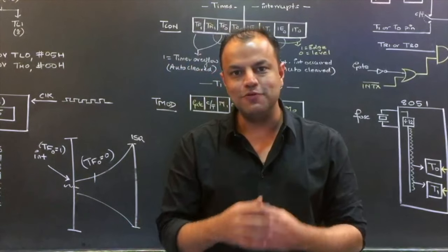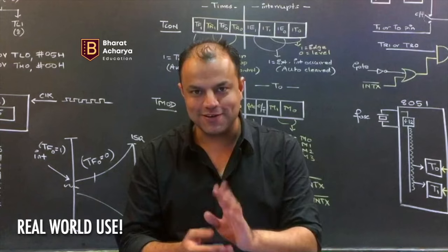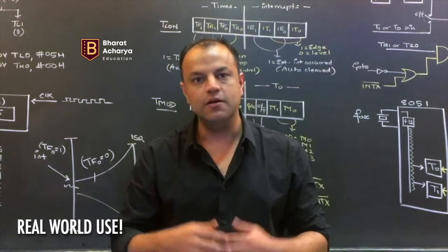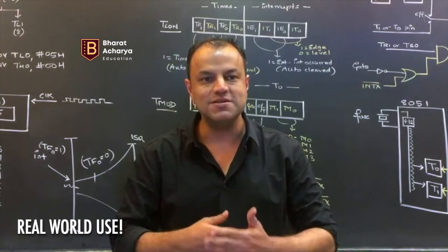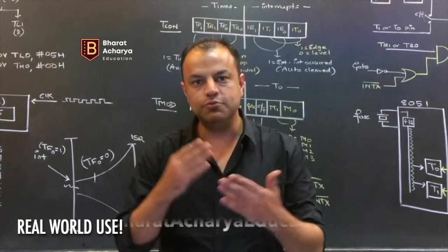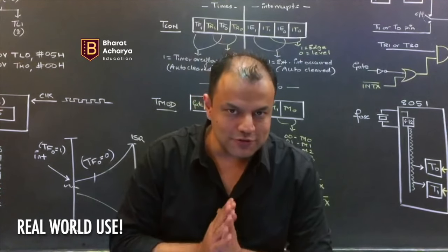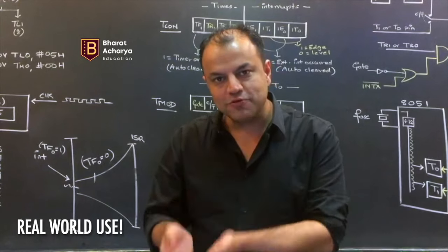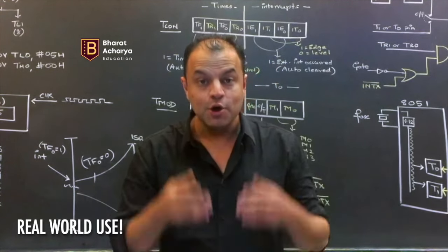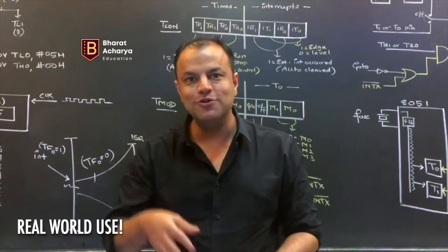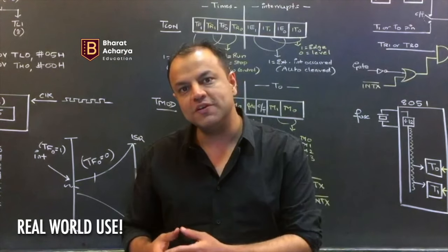Take a simple example of a microwave oven. Now, in an oven, you put food inside, you shut the door, you select 30 seconds and you press start. What happens? There is a delay of 30 seconds for which cooking takes place. A timer starts, waits for 30 seconds and then stops the whole cooking process. So who is going to make this delay? If you use a software delay, you have engaged the processor for this operation. If the processor produces the delay, who is going to rotate the dish? Who is going to control the temperature? Who is going to display the counts on the screen, the time, the seconds on the screen? So for all that, you need your processor to be free.